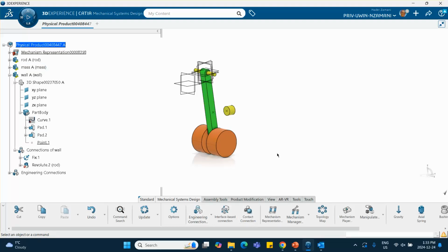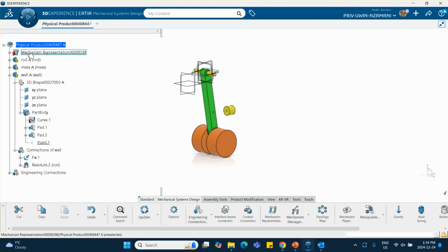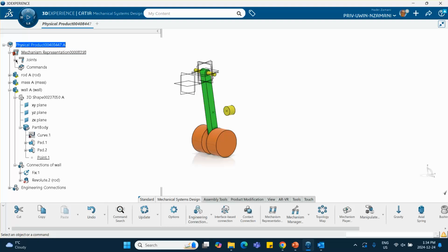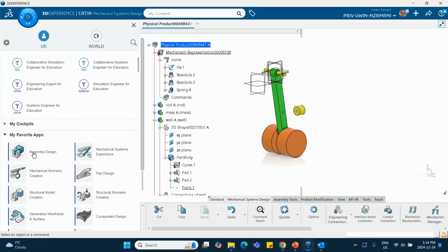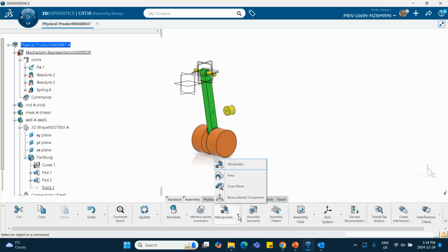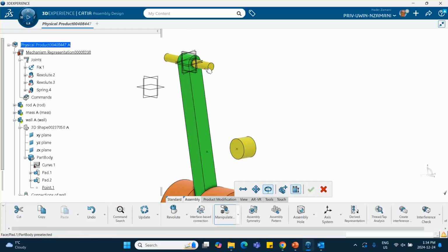So let's go ahead and, oh, material. Before I do that, well, actually we can do it now. So let's go to, maybe the best way is to move and manipulate. And in order to get hold of that, the best way is to go to the assembly. Let's go ahead here. Let's go to the assembly, and then I do a manipulate. Make sure all the constraints are respected. So check this box, and then you can, for example, rotate about an axis, and the axis that we're going to select is this axis.